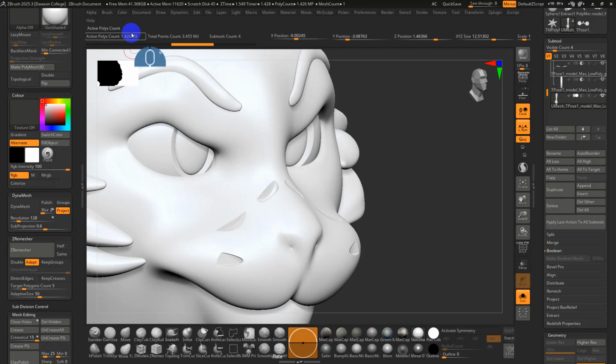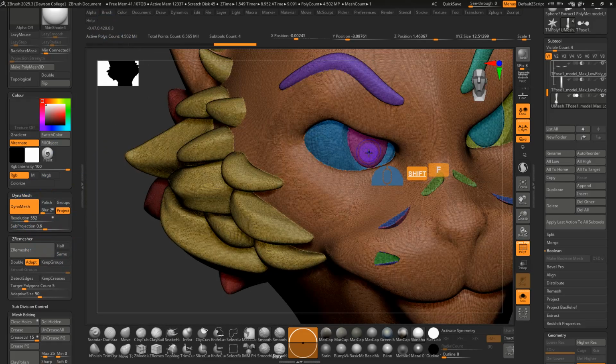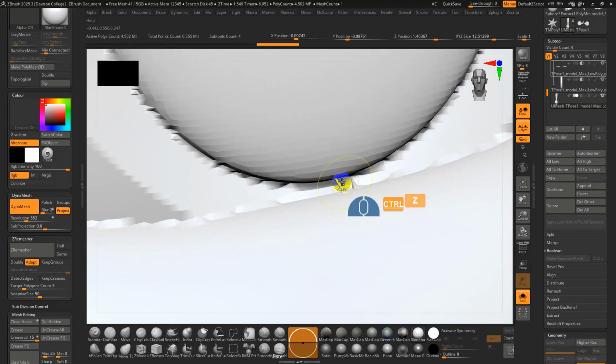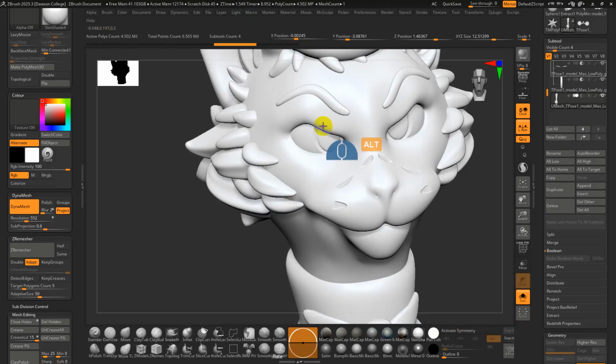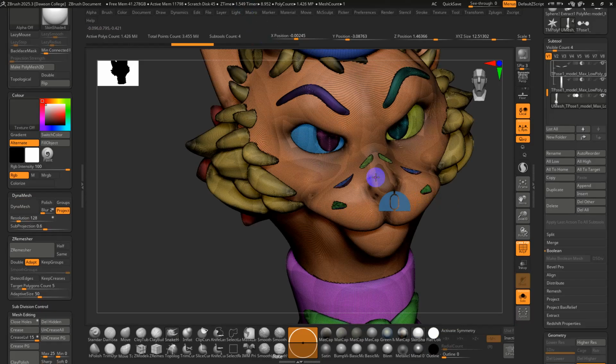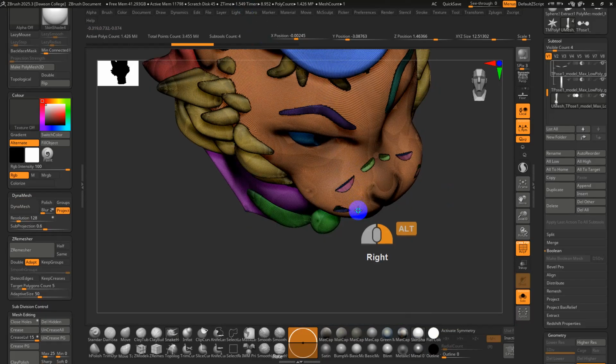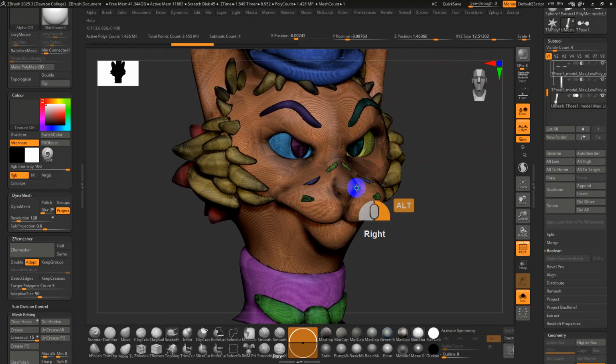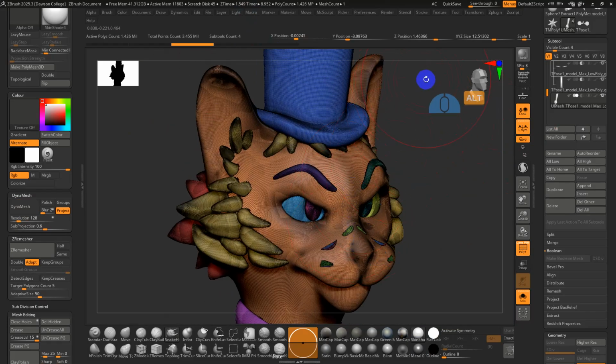And the resolution also wasn't high enough. So I want to usually meet or exceed the current poly count. So I'll try and up the resolution slider and hit Dynamesh again. And I think this will give me a pretty good result. So yeah, this looks pretty good overall. And even with Dynamesh, sometimes we'll see little jagged edges, and that should be okay. Sometimes we're getting little projection errors, but like I said, I usually do this if there's a big problem. But in this case, I found the Boolean version of the model is actually pretty clean. So whether you're starting from this Boolean mesh or a Dynamesh of all your parts, models over 1 million polys can be very heavy for the 3D printing software.